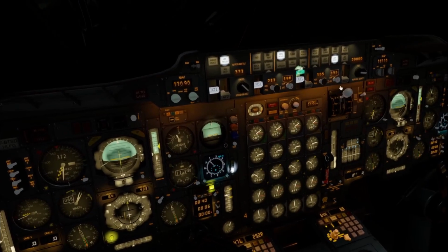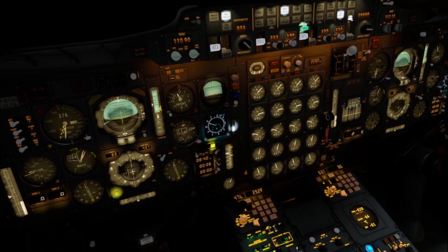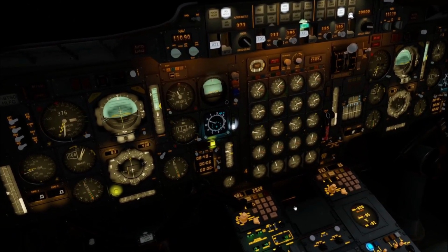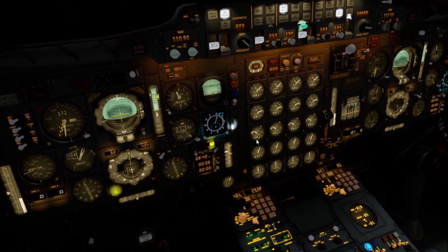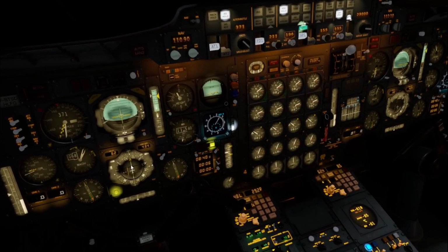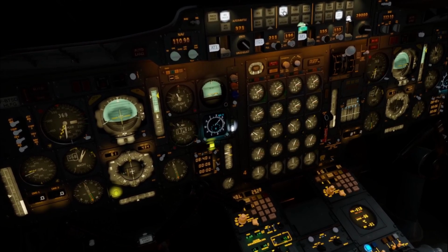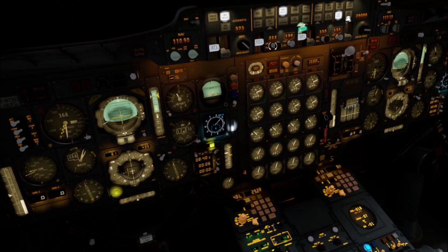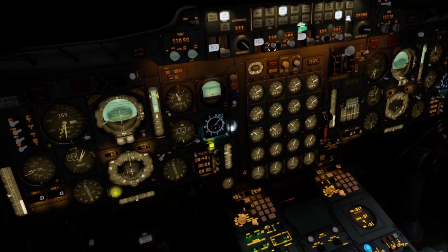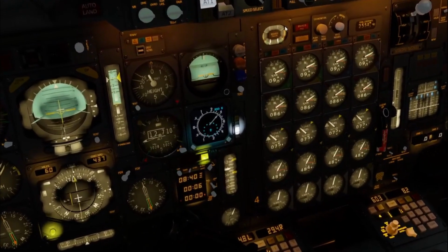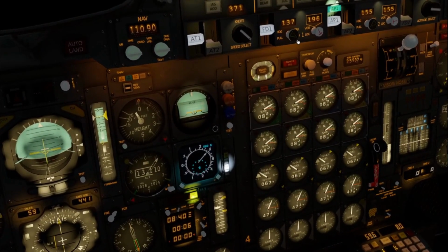And we can go a bit higher. Let's go to 29,000 feet. So we're after takeoff. We are getting closer to that first waypoint. I can use heading and track. So we'll do this. There is a click spot here. Put heading, hold, or drag hold, so I will put heading mode currently.